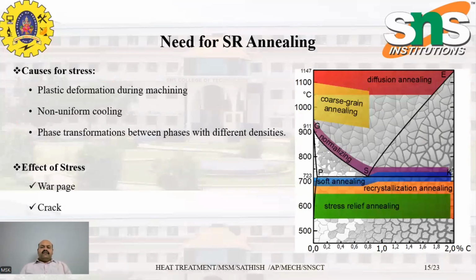The need for stress relief annealing: the causes for stresses are plastic deformation during machining, non-uniform cooling, and phase transformations between phases with different densities. And the effect of stress may cause warpage, cracks, and distortion.